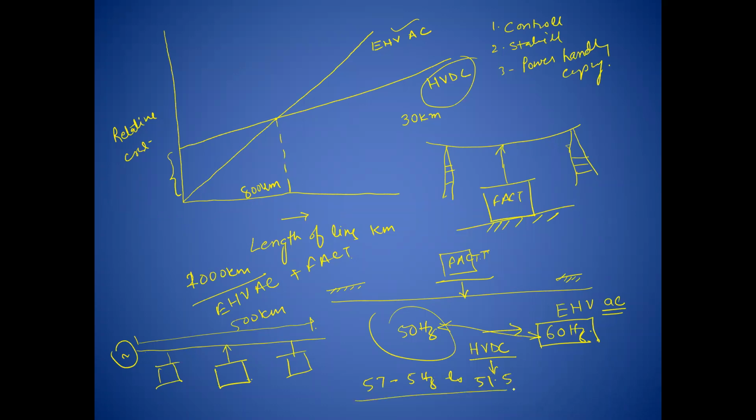This is the range over which the frequency should stay. If there is a deviation in the frequency because of a sudden change in active power, it may come out of synchronism, because we have two types of channel, that is the PF channel and the QV channel. Whenever there is a large or sudden change in the active power, in kilowatts, we will observe some change in the frequency.